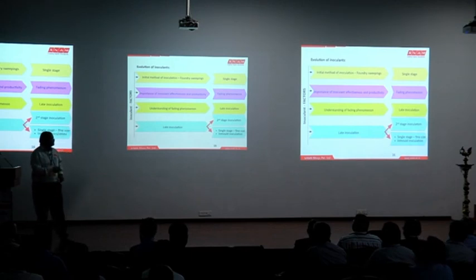So, late inoculation. And when late inoculation comes into the picture, how do you add late inoculant? Either you add it manually, or you have an automatic weighing and dispensing system, or you have inoculation done inside the mold, which we call in-mold inoculation technology.